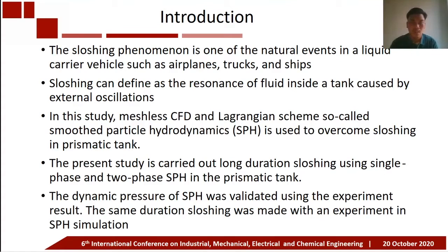In this study, long duration sloshing is carried out using single-phase and two-phase SPH in a prismatic tank. Sloshing is a natural phenomenon in liquid carrier vehicles, such as airplanes, trucks, and ships. Sloshing can be defined as the resonance of fluid inside the tank caused by external oscillation.